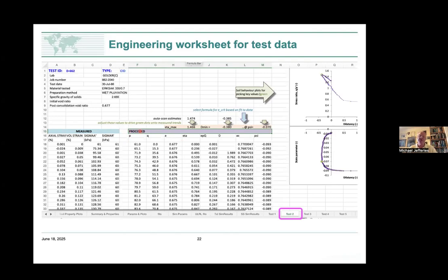That's where I've turned those measured stresses into a mean stress, a deviator stress, a void ratio, eta, which is Q over P, epsilon Q, which is the deviatoric strain, D is the dilatancy. Then I also use the critical state void ratio for this particular test, and then the state parameter. And this processed data is what I use to generate my graphs.